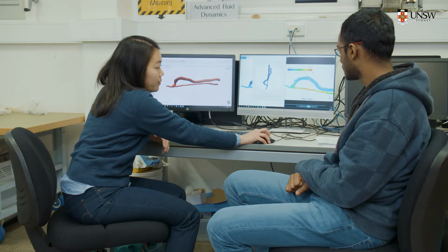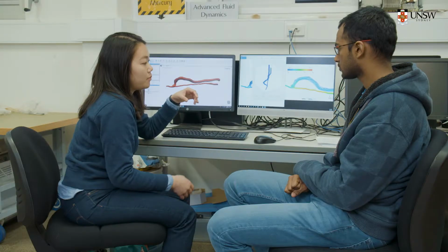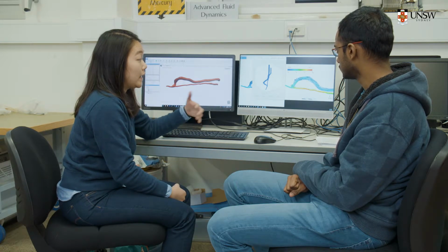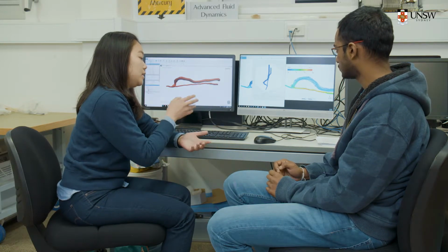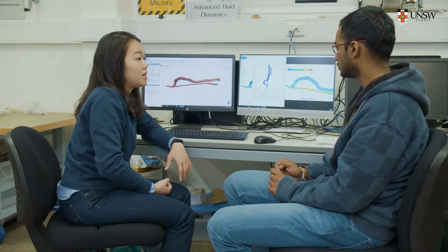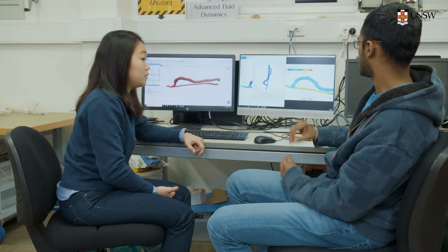So this is the CFD velocity streamline that I have. If you look at this image, there are two inlets. That's the boundary conditions, and you can see that flow is flowing out from the vein. So essentially, in CFD we put in different inlets, different boundary conditions, and the boundary conditions are the same as the patient. So basically, the velocity of the blood is the same as the patient when we took the scan. So it's trying to make it more patient-specific, because it's quite important for AVF to be patient-specific in that sense.